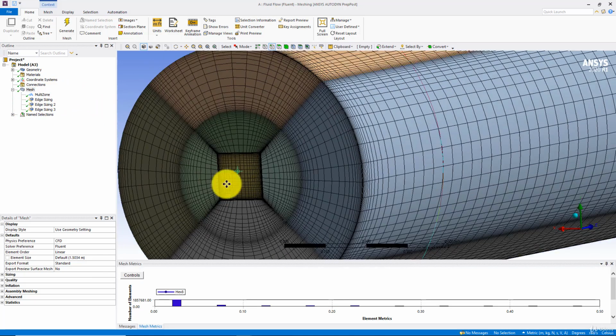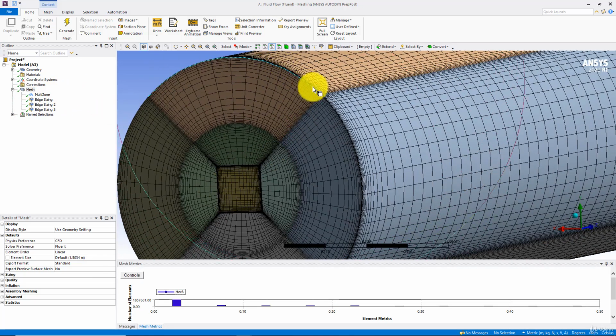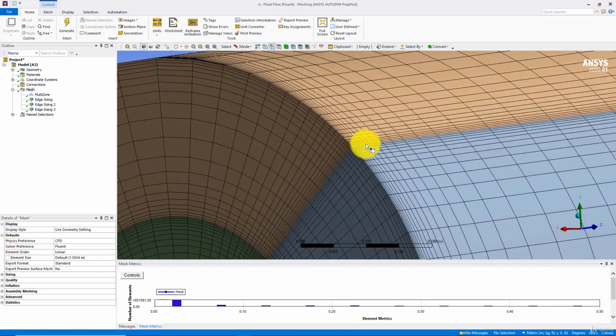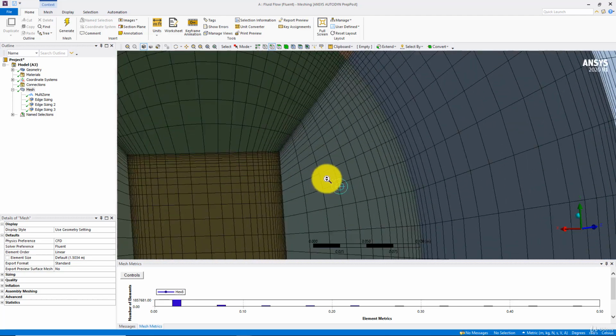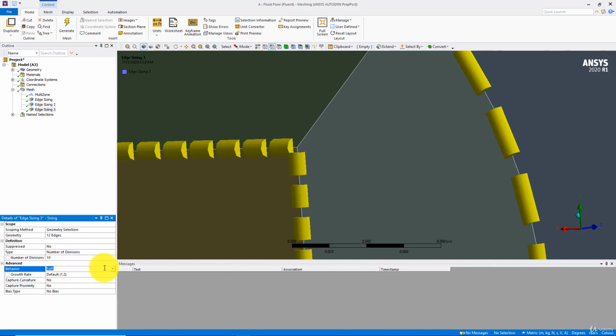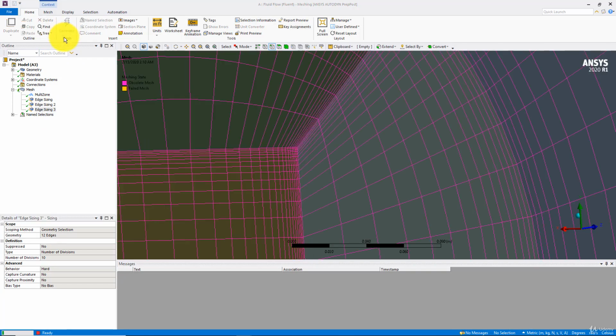And you can see that almost the things are the same, but I can observe one thing, that the mesh is refined too much here. And secondly, we have this biasing on these edges, which we put as uniform. So maybe you can say this is soft, so we can put it hard, and okay, we can generate it again.